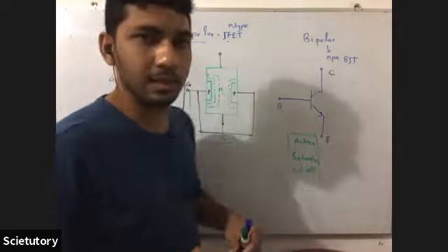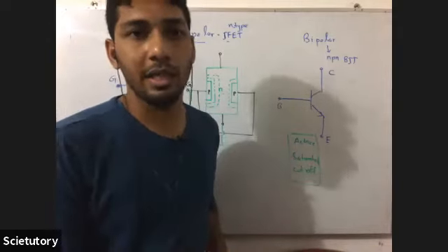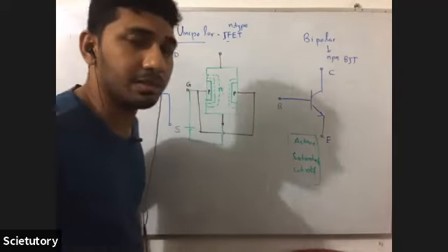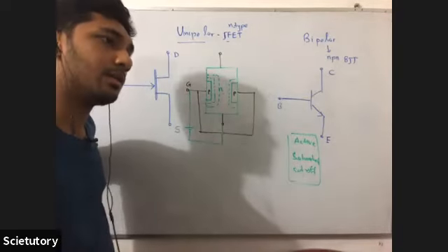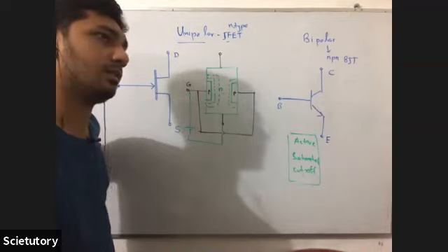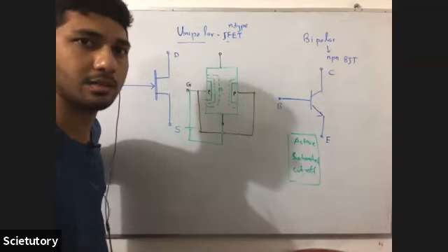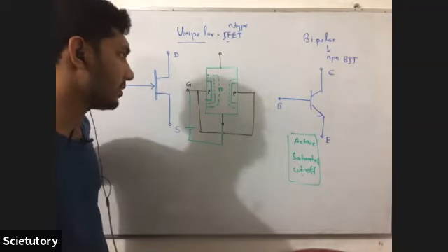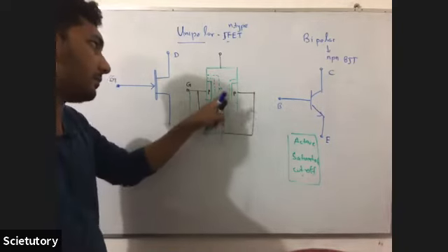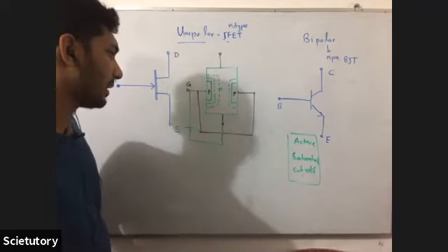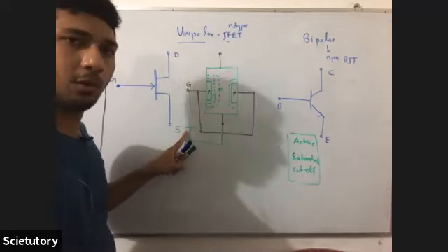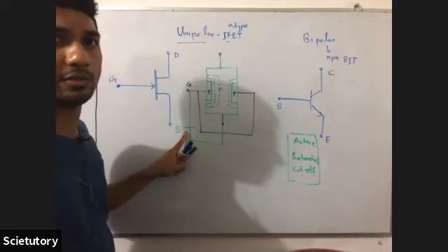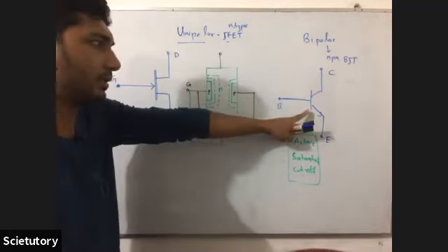If you increase the thickness of the depletion layer, the channel becomes narrower. Due to the reduced area of cross-section to carry the current, the resistance of the channel is increased. That's how you control the current. So you actually control the whole circuit using this voltage. That's why it's called a voltage controlled device. But is it voltage controlled?